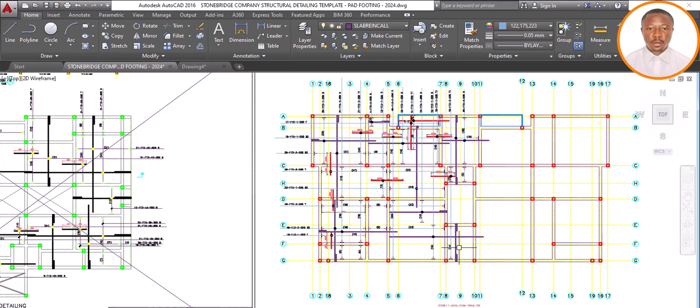So let's finish this as we round up this part 4, which is the last part of the slab detailing of this structure. As I've said, the reason why we are not detailing this other aspect, where my cursor is, is because they are typical. It is semi-detached, so what we have where we have detail is the same thing as where we have not detailed. When you get to site, all the engineer needs to do is repeat the same thing on this other side. You might be wondering why we are not detailing this aspect, but if you look at it very well, they are the same thing, just a type of building we call semi-detached. So at the site they can do that one. All you need to do is repeat the reinforcement here, as simple as that. So let's finish up as we call out this last reinforcement.